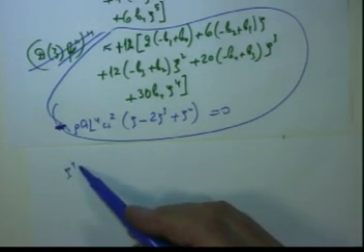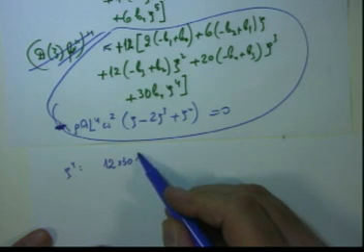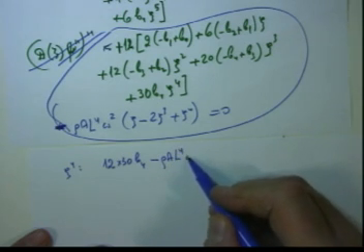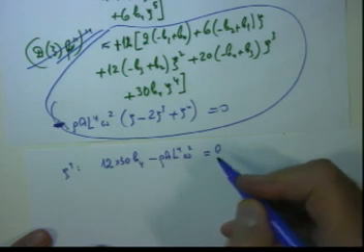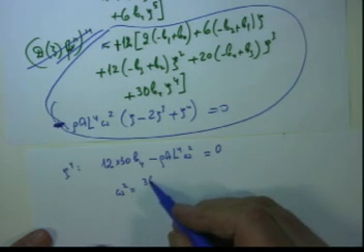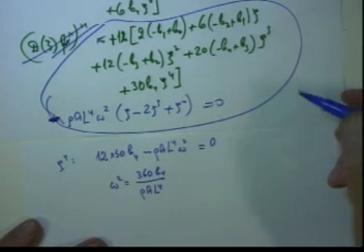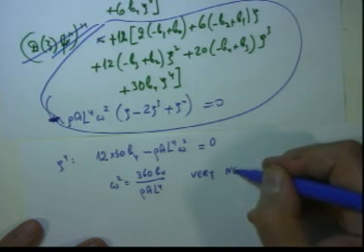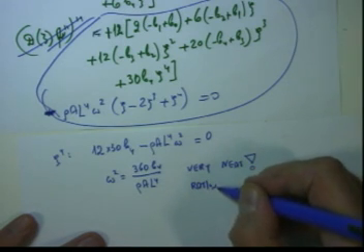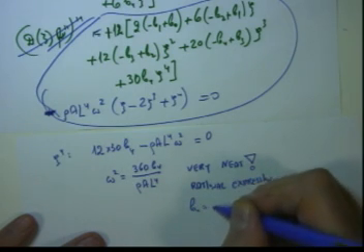So let us start with psi in fourth power. It will be 12 times 30 b4 psi in fourth power, then minus rho A L in fourth power omega squared. This equals 0. So omega squared equals 360 b4 divided by rho A L in fourth power. Very neat, rational expression. b4 is arbitrary.